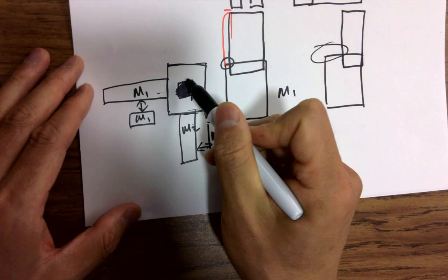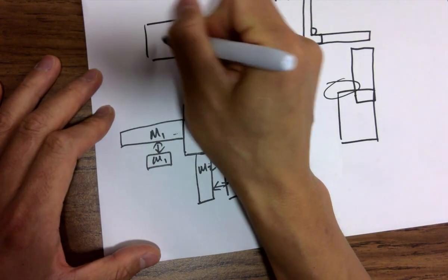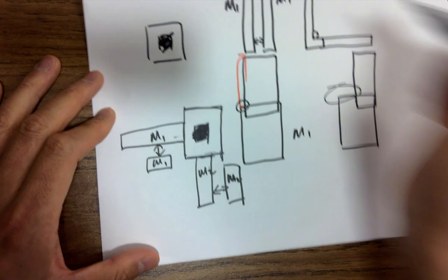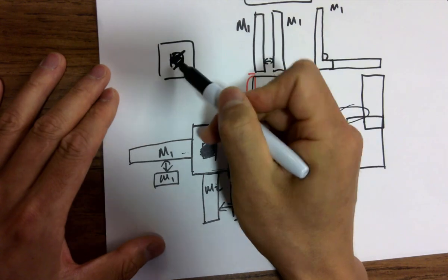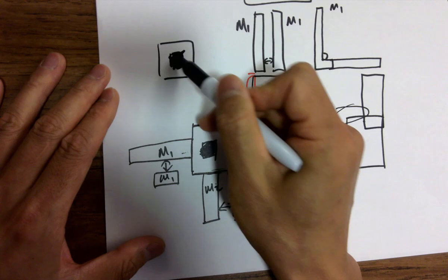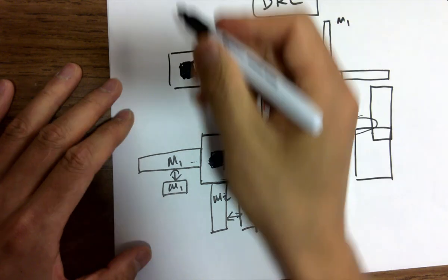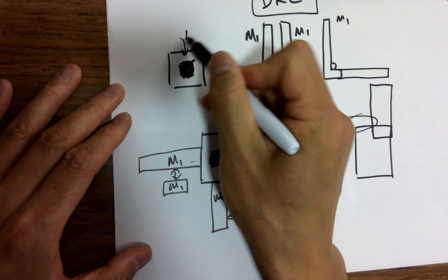So in that case, if you left click and grab this node without a metal wire, you just grab this thing, it has this outline and a little via in the middle. It's from the library, so the tool did it for you. And then you select metal 1. You left click in the library and select metal 1. So you left click first.